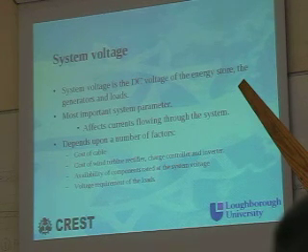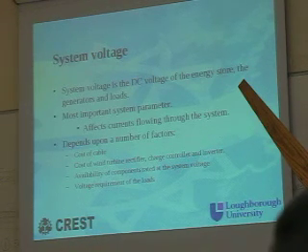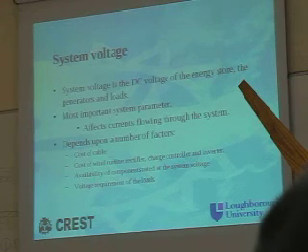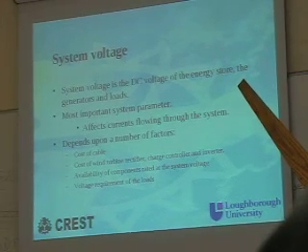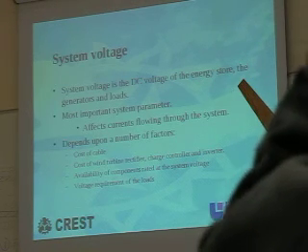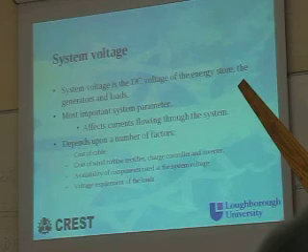It will affect a lot of things: the cost of the cable, the cost of the rectifier, but it does affect the availability of components which are rated at that voltage. So 12 volt stuff is pretty easy to find because we use it in cars, whereas 48 volt stuff is pretty difficult to find because not many people use it much.